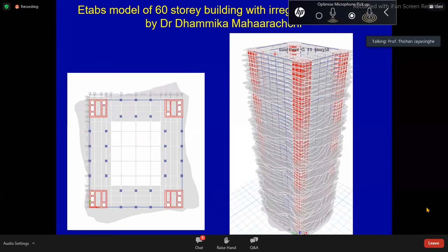And so if you keep 2 times diameters with 2 meter piles, then again you'll see, by maintaining 2 times diameters as the spacing, you can still keep 2 meter spacing between 2 adjacent piles, and that would be sufficient to ensure the drilling of one pile not damaging the already completed other pile. Because we are using high strength concrete, the chances of such damage is also less, because we will be using very high quality cutting tools to create piles.